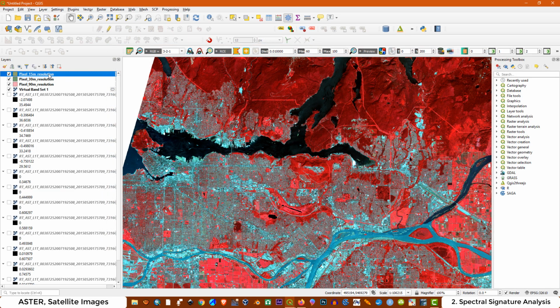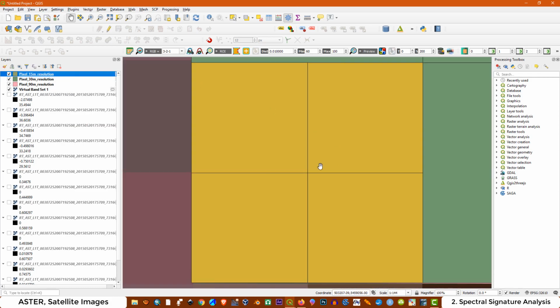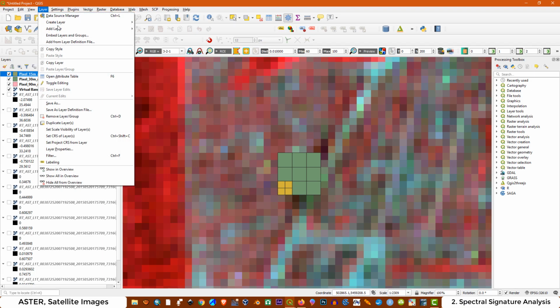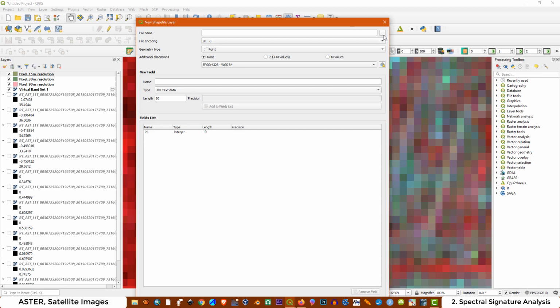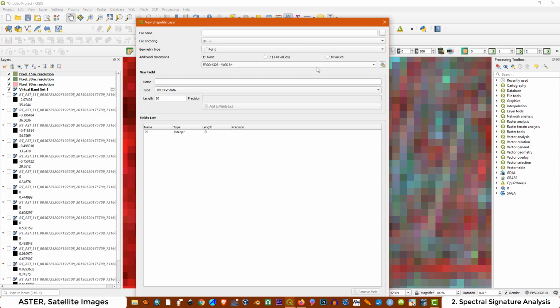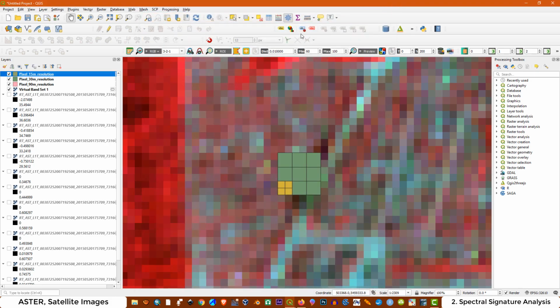Now I'm going to zoom to this vector layer. I created these different layers with Layer, Create Layer, New Shapefile Layer. Then select here the name of the layer. In this case I put these names. Then what I did is select the polygon and then the reference coordinate system. It was this one. And then OK, and you are ready to edit the layer.